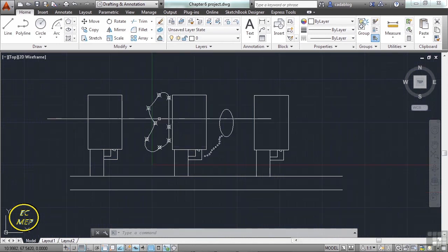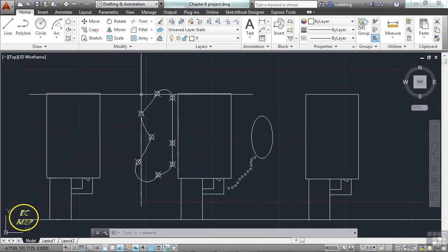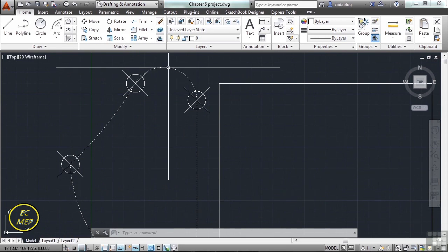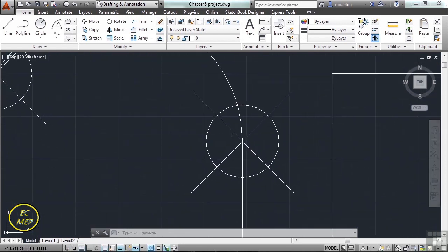Now sometimes though, when you erase your objects or you're doing some other work, you're zooming in and out and things get messed up on your screen. Your drawing's not really affected, but something's just kind of screwy with your computer. Sometimes, for example, a circle or an arc will get segmented, meaning it won't be a round, smooth curve. It'll be just a series of jagged lines. That happens. Or when I zoom into these points, they're too big. Things like that. Or sometimes when you delete an object, there'll be a screen remnant, meaning your video card on your computer just didn't completely render your screen properly.